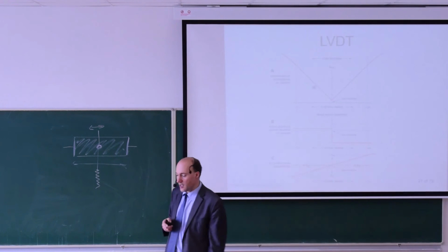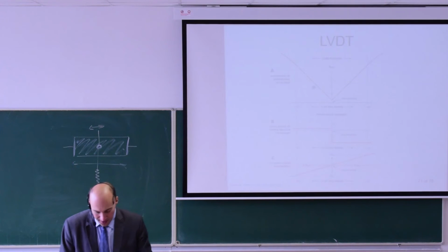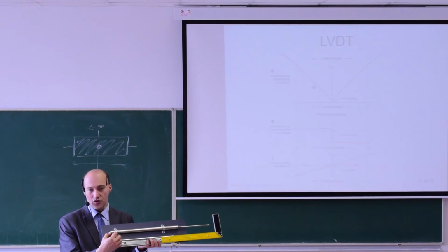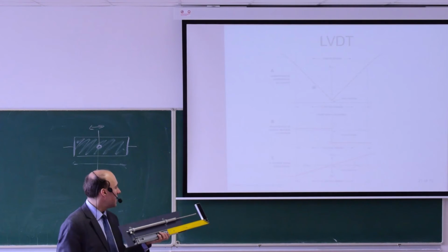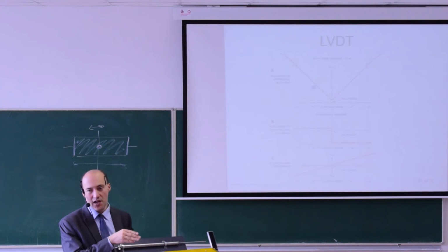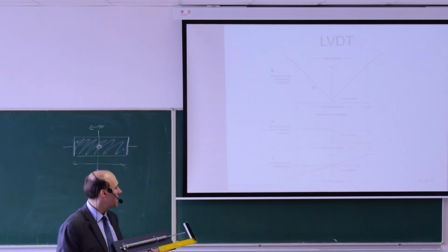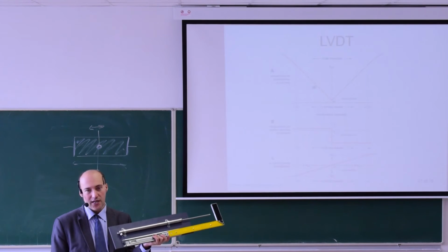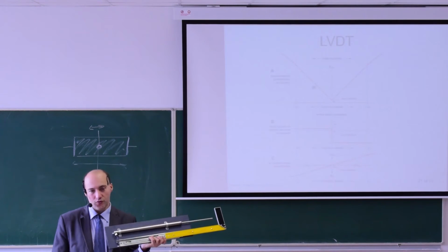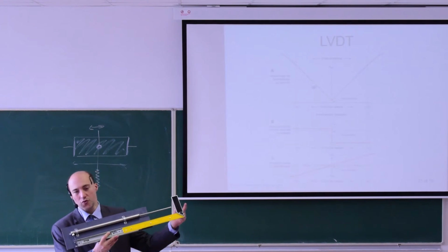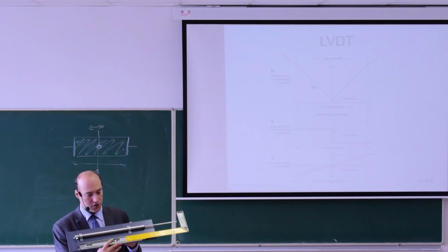And this is exactly what is happening here in the sensor. So this sensor has embedded electronics, so it can work with the phase shift and with the voltages, so the output is a nice linear dependence. Moreover, this sensor has a current output, so the current from 4 to 20 milliamperes corresponds to position 0 to 150 millimeters.